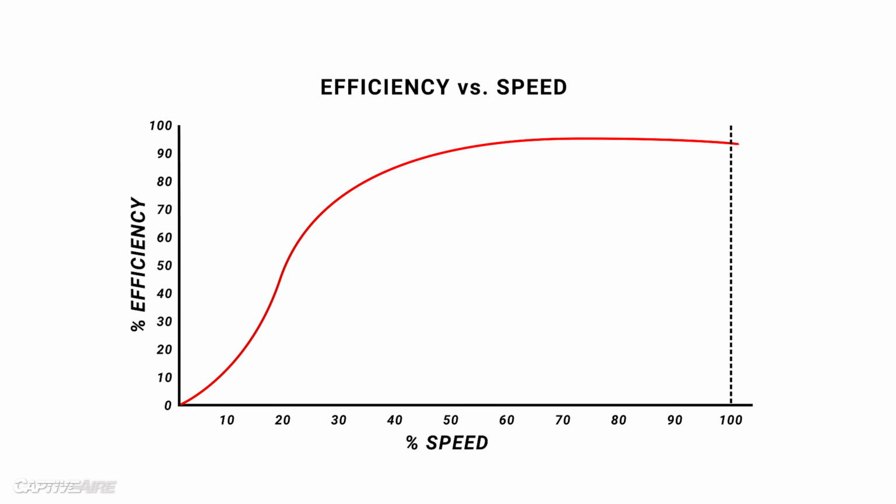It's another reason that we limit our min RPM, because when you start to reduce the speed too far down, if you have a motor that's designed for 1750 RPM and it's only running at 25%, so 15 Hertz, it's gonna have a lot less efficiency down there, which can hurt you and use quite a bit more energy as well.